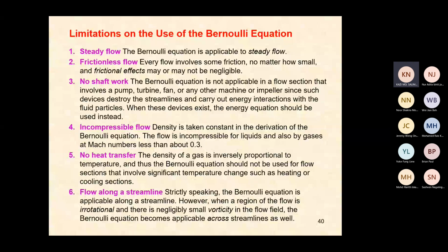So here are the limitations, and you can see one: these sudden expansion flows. This is the backward facing step. Similarly, like a forward facing step, in both cases Bernoulli's equation cannot be valid. There are different equations for those. And a long narrow tube, if points 1 and 2 are two different points, then it's not valid.